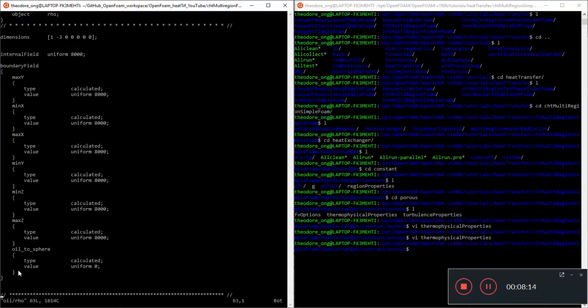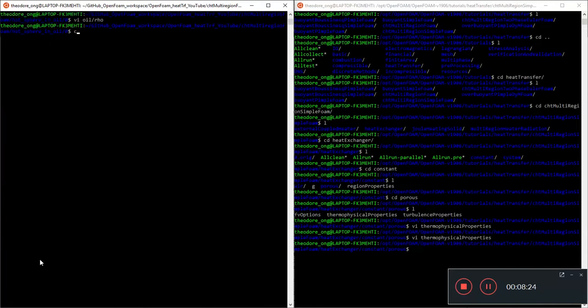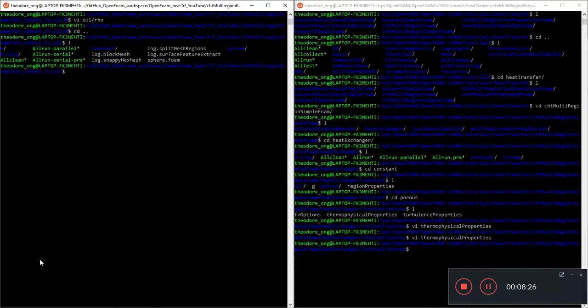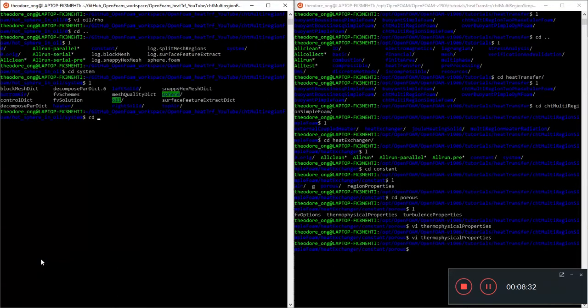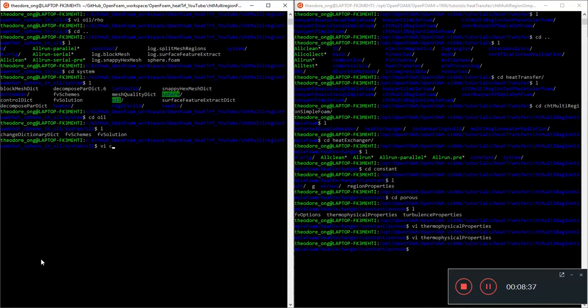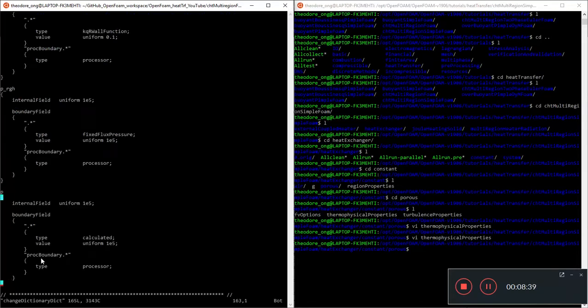Yeah, so basically, anyway, as I'm doing this, just a thing: why is it here? The reason why it's here is that in buoyant pimple foam calculations, there is always a need to change the density every now and then, because otherwise there's no natural convection.